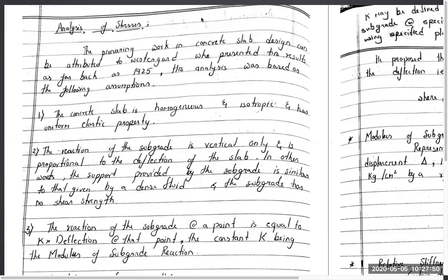So during summer the slab expands, during winter the slab contracts. Because of this, there is a frictional stress which occurs. Then there is daily variation. There is warping, curling of the slab upwards or downwards. Because of that, warping stresses are occurring in the CCP. Apart from temperature stresses, what are the different stresses? Wheel load stress. Yes, wheel load stress is the primary, higher magnitude stress which is caused.